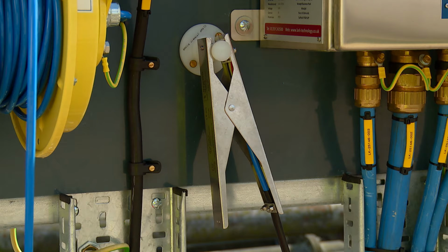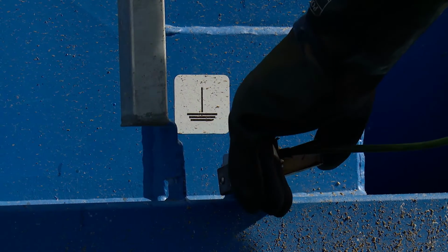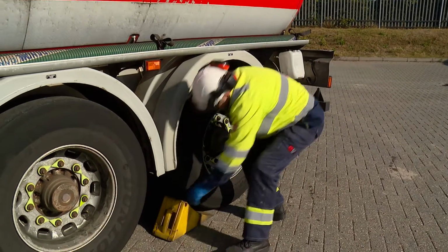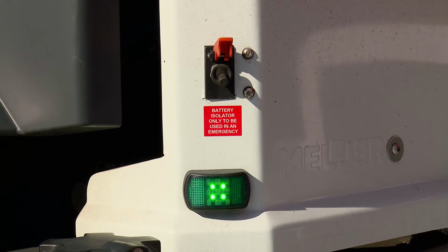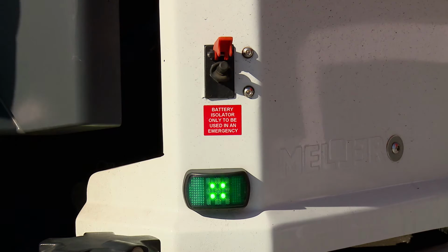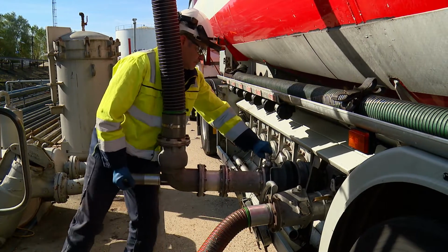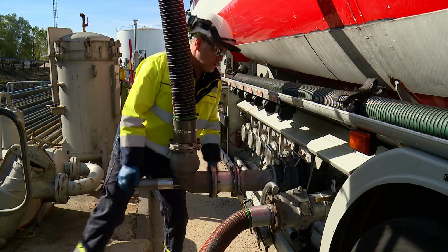It is, therefore, vitally important that earthing clips and cables are connected before any other operation and transfer commences. It is also important that wheels are chocked, or a brake interlock system is utilized, and that all electrical connections within the vehicle are isolated using the electrical master switch. Connections can be made once site operators are satisfied that all criteria have been met by the product.